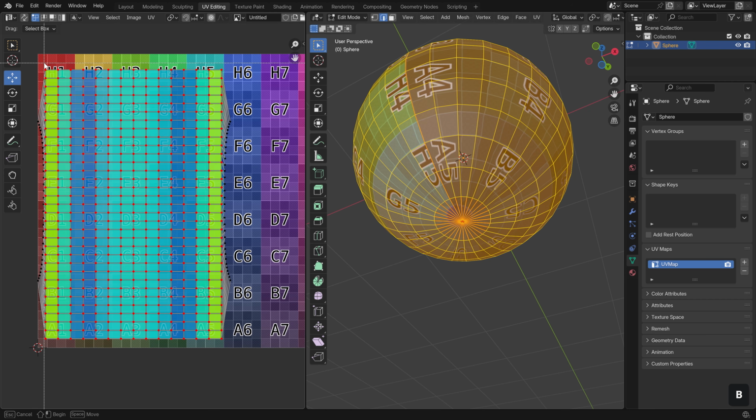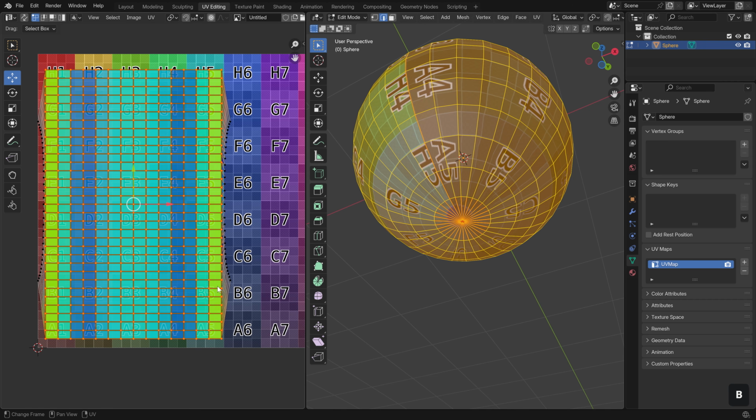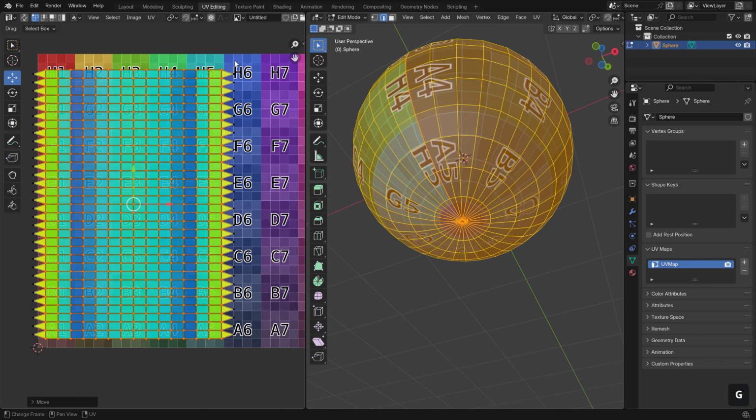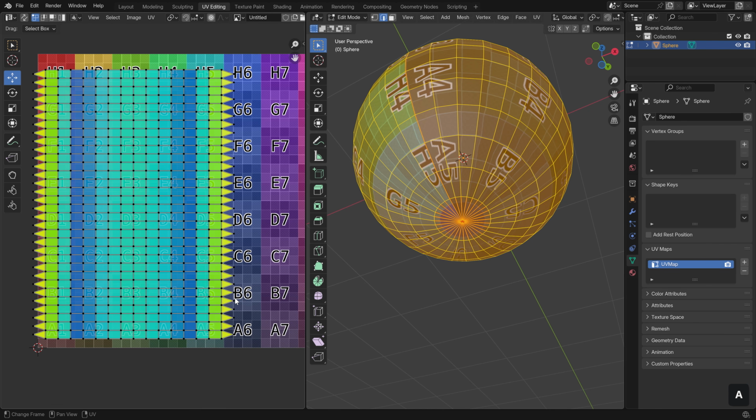Now, what we're going to do is select all of these points and move them, so we'll update the UVs since we enabled Live Unwrap. As soon as we do this, you can see all these triangles get updated since they're trying to reposition based on the rest of our unwrap. And now we get a clean unwrap for all of these triangles. Let's now press Alt-P to remove our pins. And let's now pack all of this into the UV tiles.